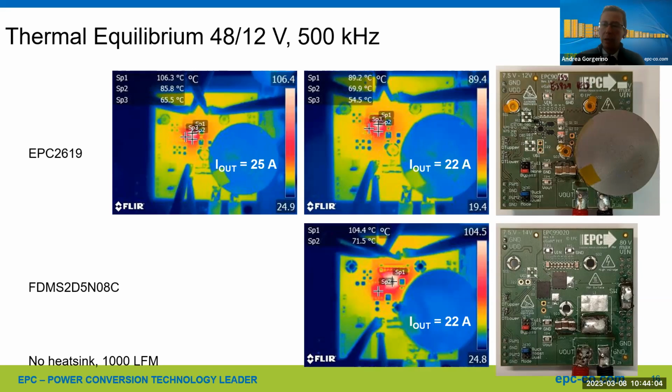And the last loop is you want to minimize the gate loop inductance itself. It's still important, although it's third. And there the concept is the same. In this case, you have the gate driver right here, and you want to use a similar concept. So you have a trace that goes right there to the gate. It's a very, very small distance. And then right underneath, you come back with a little plane and close the loop on the gate itself.